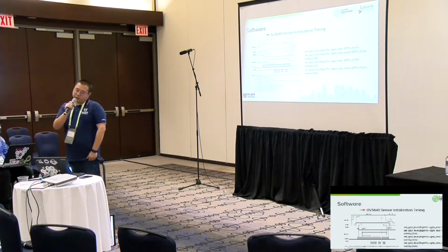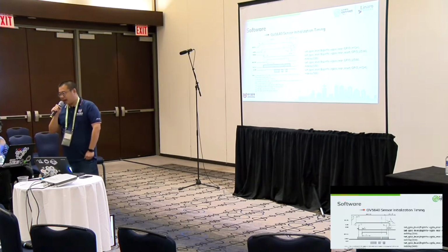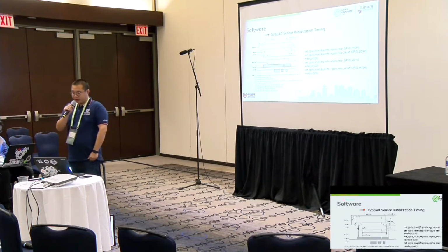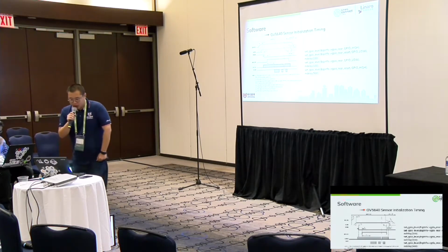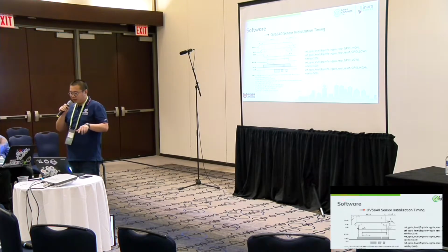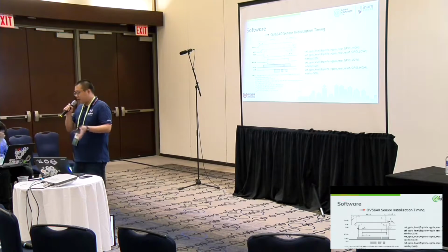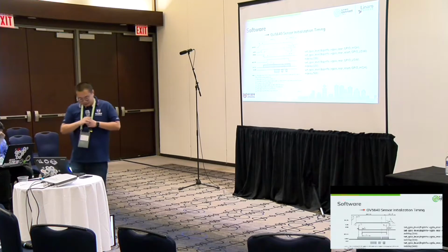So in software, we just care about power down and reset. We use a set GPIO level function to do that. But the pin definition is defined in the device tree, so it cannot be modified in the user space.